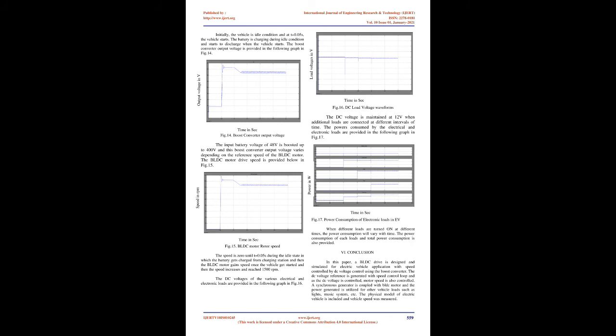The %SOC waveform of the battery is provided below in Fig. 13. Fig. 13: %SOC waveform of battery. Initially, the vehicle is in idle condition and at t equals 0.05 s, the vehicle starts. The battery is charging during idle condition and starts to discharge when the vehicle starts. The boost converter output voltage is provided in the following graph in Fig. 14. Load voltages in V. Fig. 14: boost converter output voltage.